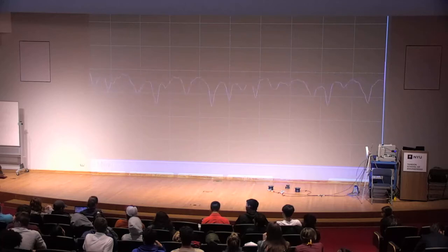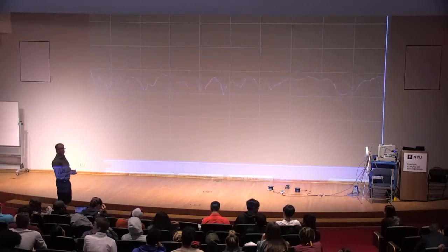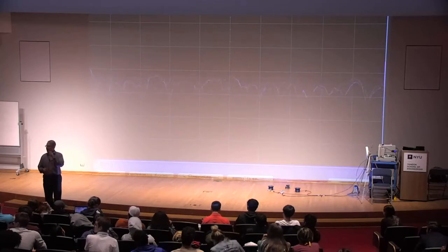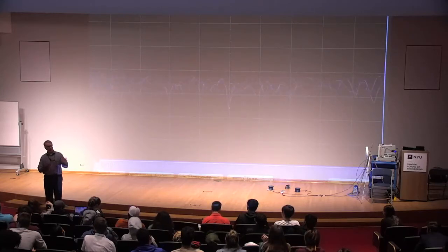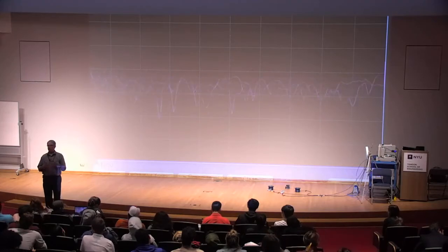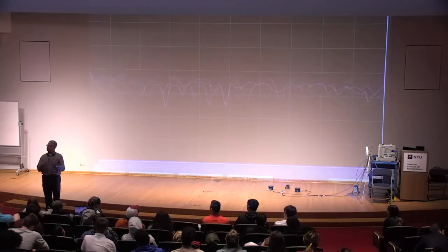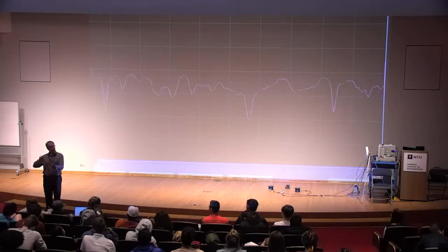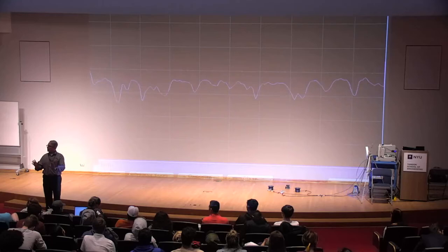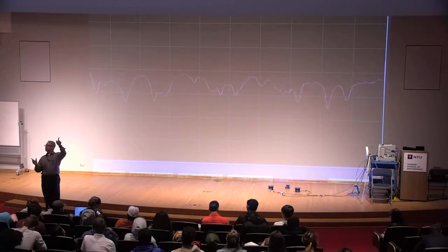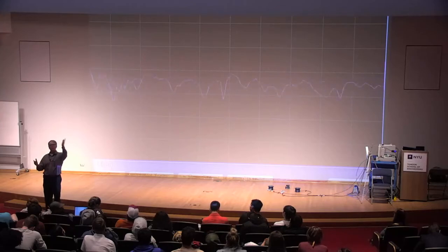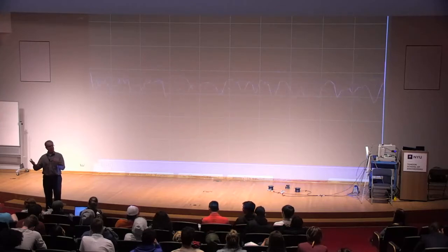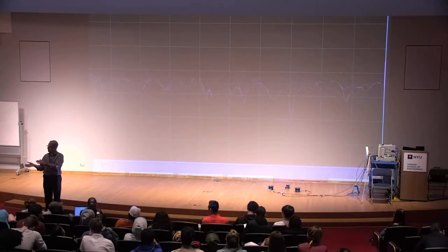Oh, that's an excellent question. The question was, what's the difference between 5 gigahertz Wi-Fi and 5G? The Wi-Fi band I showed you before was 2.4 gigahertz. Gigahertz is the frequency, the sine wave that's actually transmitted. So when you talk about Wi-Fi at 5.6 gigahertz, that just means the carrier frequency is higher. Effectively, you're negotiating with the access port, which is somewhere up here maybe, or out in the hall, and the access port is telling you it's better for you to work at 5.6 gigahertz. It's essentially moving you to a certain frequency to communicate.